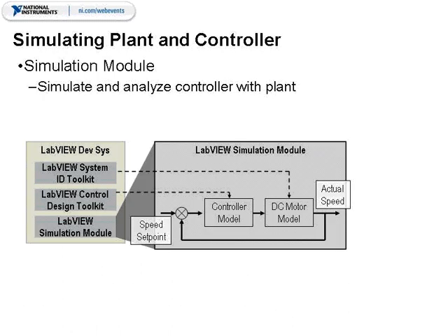The next step, once we've designed a controller for our plant, is to actually do offline simulation using the LabVIEW simulation module. This will allow us to view a time response to the system to arbitrary inputs with advanced numerical solvers, as well as add a more high-fidelity plant model, for example, simulating nonlinear characteristics of the model or limitations of the controller, such as the output saturation. The LabVIEW simulation module allows us to represent closed-loop systems in control block diagram form directly within the LabVIEW diagram.